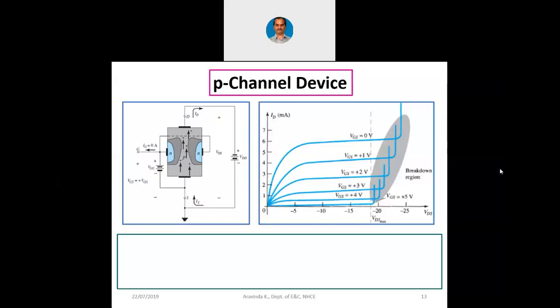I had given an example that if my head can handle 100 kg weight, then I should not always handle 100 kg. I can safely handle 50 kg weight. Daily, if I handle 50 kg weight, my head is manufactured to handle 100 kg weight. That way, my head is safe. Same way, in the circuitry, if there is a voltage, we will choose a device which is capable of handling double the voltage. Otherwise, the device will break down if such situations come into picture.